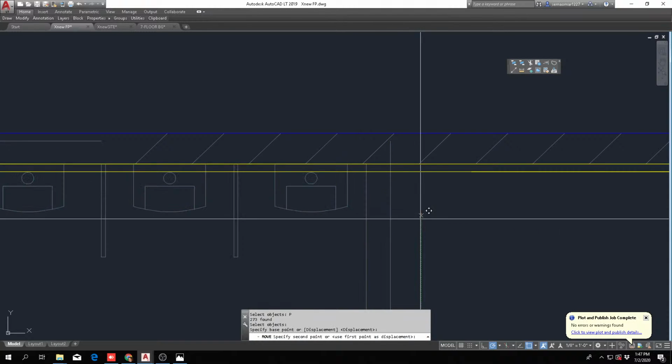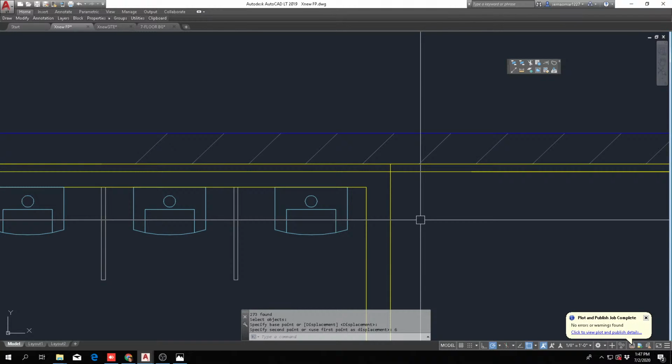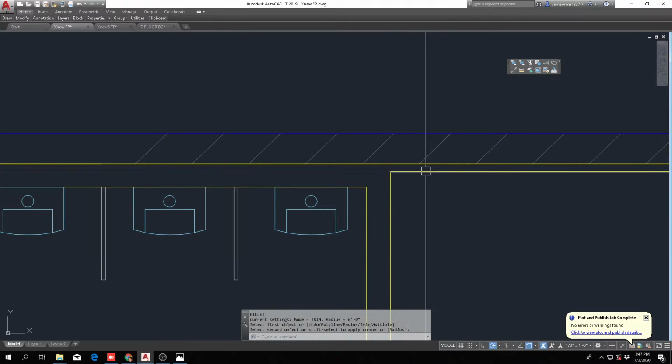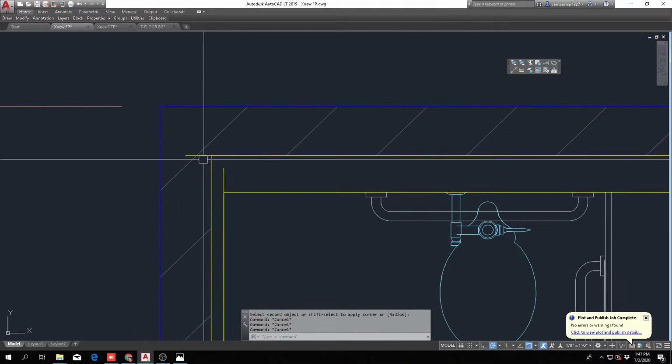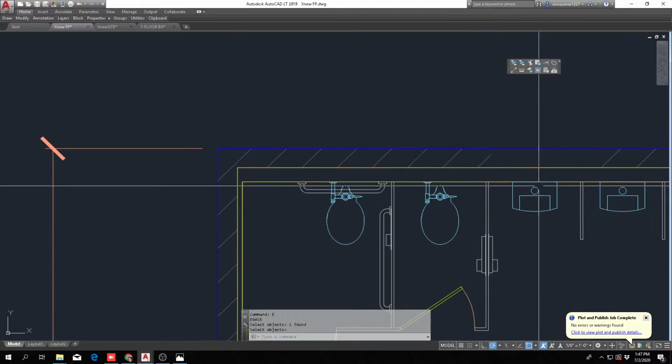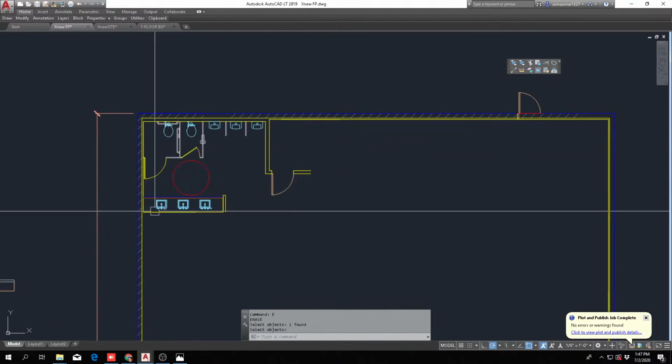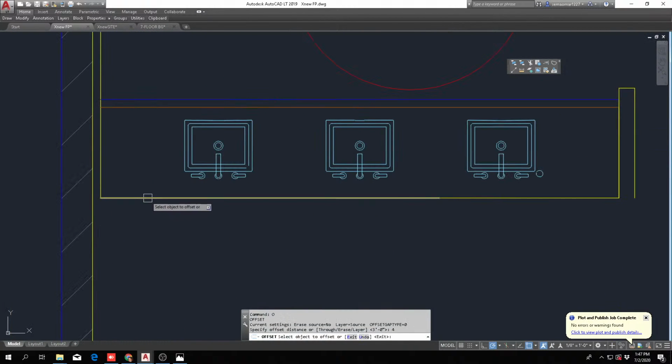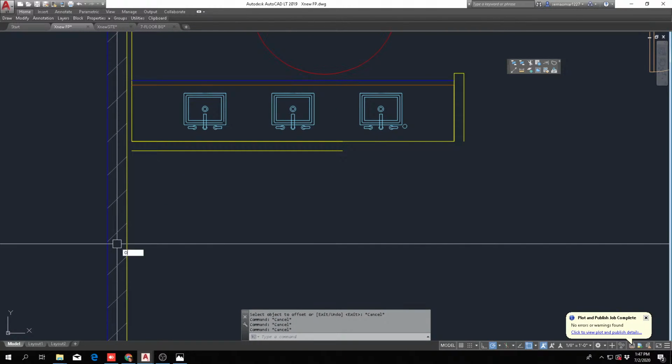So that's why you always have to put a furred wall to put all your plumbing stuff. So in this case, I'm gonna go with 6 inches. Why? Because that's the dimension of 6-inch metal studs, so they can run their plumbing inside that wall. Okay. On this side, I'm just gonna put a 5/8 wall,